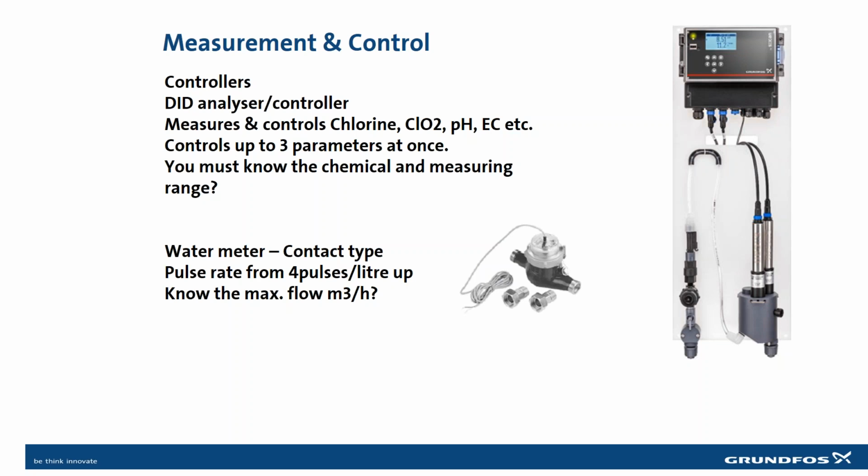The thing to check, particularly if you're using digital dosing pumps, is what the slowest dose rate is, minimum flow. If the pulses get too far apart with the digital dosing pump, the dosing pump doesn't run continuously. It will see a signal and start to run, but because it doesn't know when the next pulse is coming in, it stops and pauses, and you get very intermittent dosing coming out. So it's important to know both your min and your max. When sizing, most important to know the max and to set up the right pulse rate.